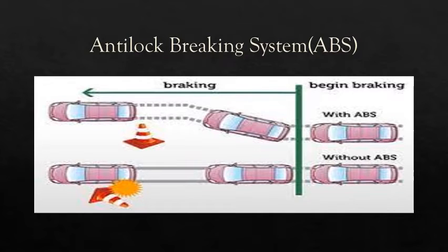In this case, when brakes are applied in a panic situation, the rear wheel gets locked and the wheel skids. This effectively increases the braking distance. ABS reduces the skid effect and helps the vehicle to stay on course. The heart of ABS is the microprocessor based unit which senses the wheel speed and modulates the braking on the wheel. The system takes over the braking action only during sudden braking.